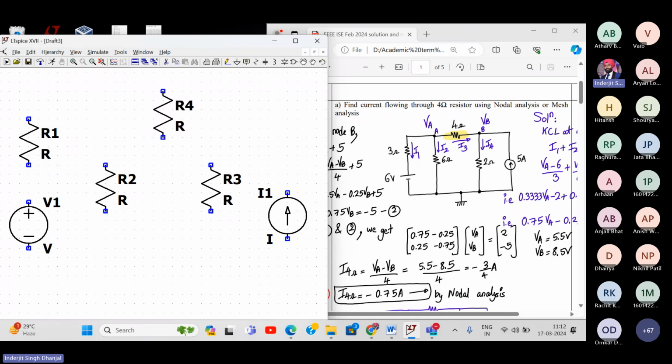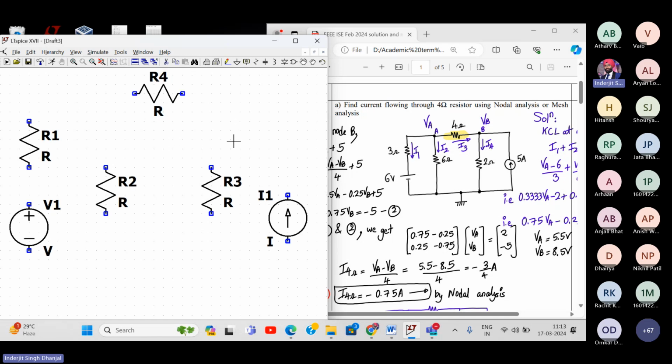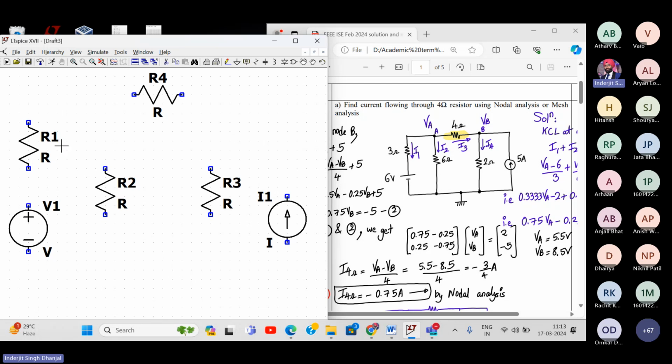So for orientation, you can press Control R. It will orient to 90 degrees. So you can place it over here. This is the way we can add the resistors. So please add the resistors in the network. Tap it once and then instead of pressing escape, tap it twice, wherever you want to add it. For rotating any component, you press Control R from your keyboard.